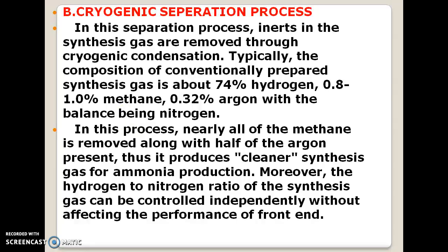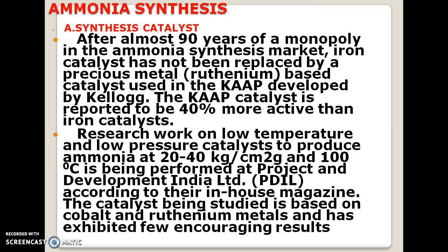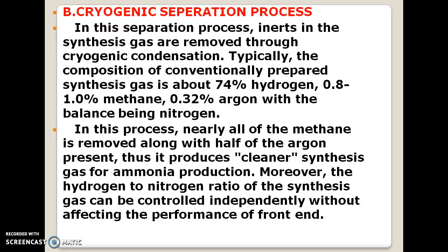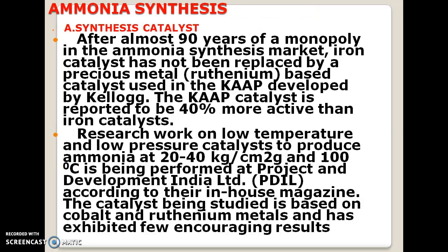So cryogenic separation is required because ammonia at 15 bar can condense at 40 degrees centigrade, whereas at 1 atmosphere it can condense at minus 33 degrees centigrade.